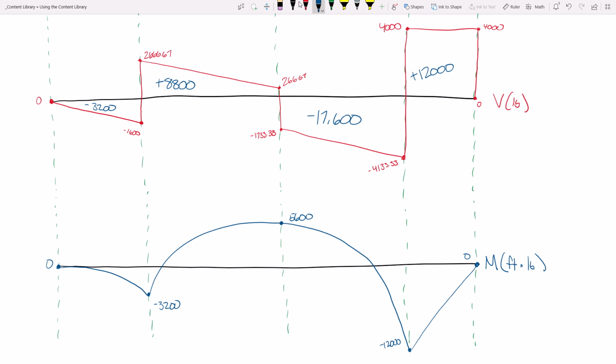For example, if you have composite beams and you have different materials on the top and bottom of the beam, you might have to check both conditions because you have different stresses on the top and bottom. This is a very common instance in reinforced concrete design. In reinforced concrete design, we put steel where there is tension in the beam. So here, and we'll talk about this later, tension is in the bottom of the beam. But over here, tension is in the top of the beam.